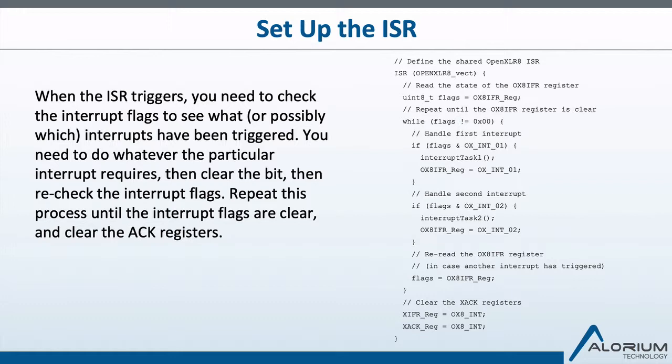If you've ever seen an ISR in Arduino before, this will look very familiar. You're just creating an ISR and having it trigger off of a specific vector. If you haven't ever built your own ISR before, this is what Arduino uses for any of its hardware interrupts. It has a vector defined for a specific ISR, and the contents of that ISR are the function that is called when that hardware interrupt is triggered.